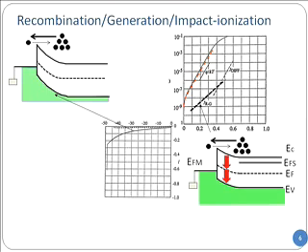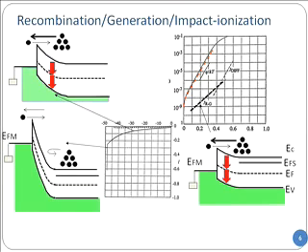What about that last piece? Impact ionization. Or what was the other thing? Zener tunneling. Well, both can happen here. If you put a high reverse bias on the semiconductor side, the electron can easily tunnel in. You can see the triangular barrier. Don't you see that? On the left-hand side, I have a huge amount of electrons on the metal side. And they can easily tunnel through that triangular barrier to the semiconductor. And therefore, I can have a huge amount of current, just like a p-n junction.